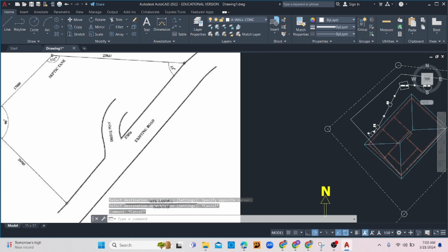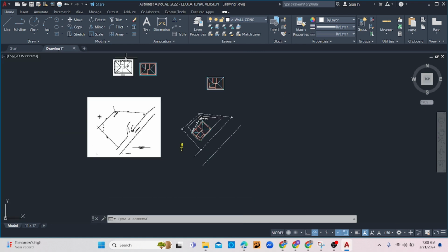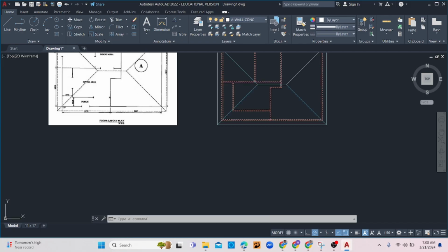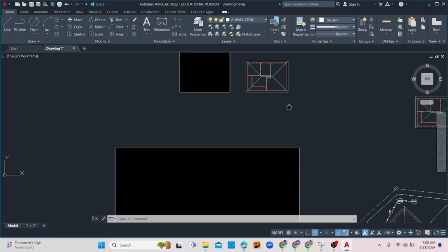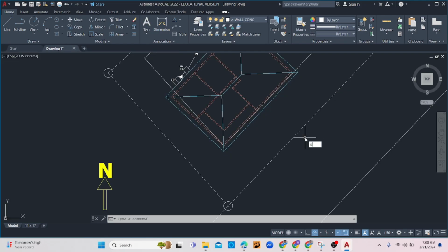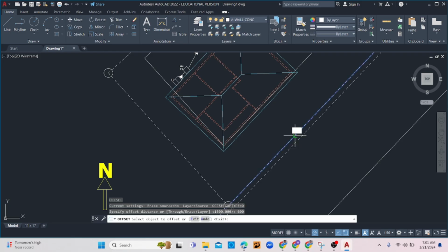Now here is where they place the driveway, but we're going to be placing our driveway so that things match up, unless here is a garage or something, living room. So we're going to sort out our driveway now. Alright, now we need a sidewalk. Our sidewalk is going to be about, well, a shaft shoulder first. That is going to be about 300, not 300, 600. So I'm going to offset this line here, 600. I'm going to then offset another 900.